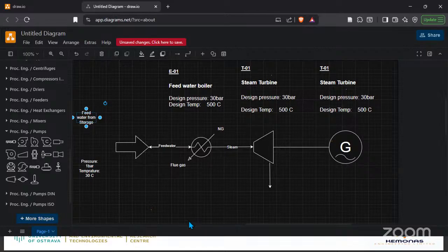So for this, we will use a single stage centrifugal pump, because there we will need much higher pressures. For example, let's say we are looking for above 60 bar, we can have multiple stages of centrifugal pump where the output of pump one is feeding pump two.